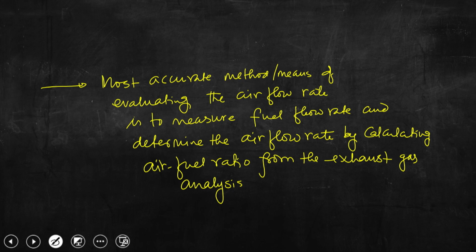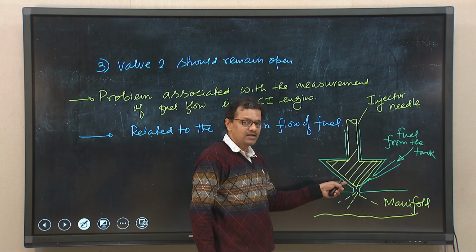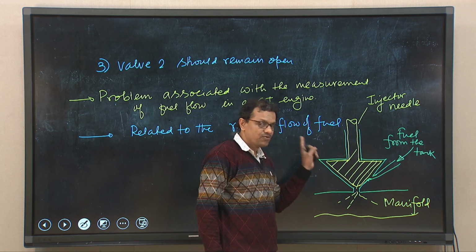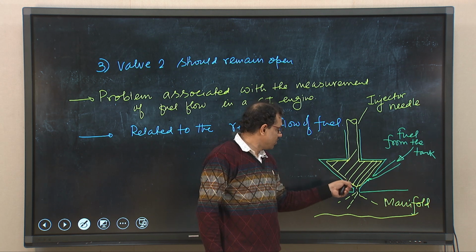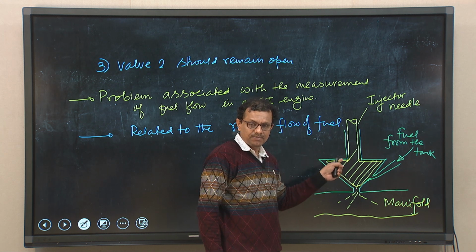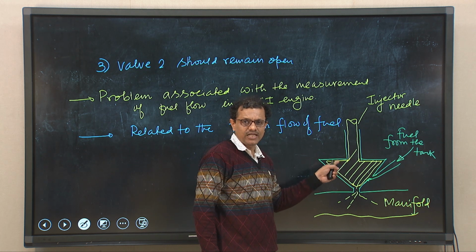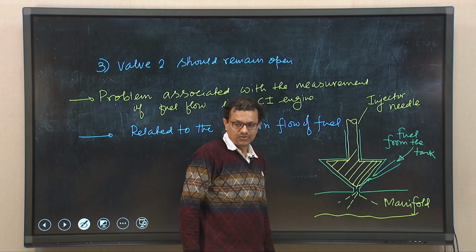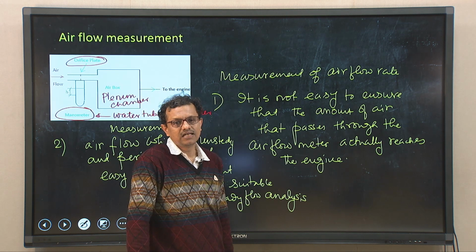If we go back to our previous slide, wherein we have shown this injector needle, try to understand that accurate measurement of fuel flow rate is necessary for the accurate measurement of air flow rate that we have just discussed. And if we need to measure fuel flow rate accurately, we need to measure the lift of this needle, and today we shall discuss one technique or method which is used to measure the needle lift.